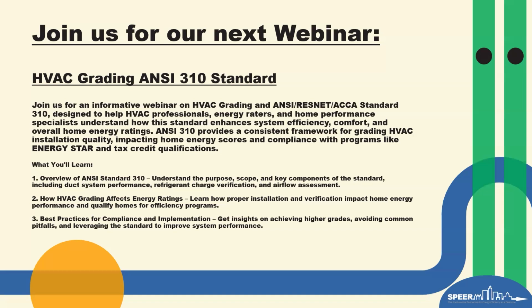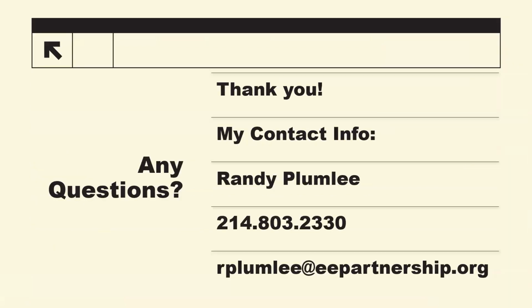If you're still doing the YD150s, if you're in an area that's on the 2018 or prior, 2015, 2012, 2009, and you have mechanical ventilation, then they're going to be doing open heart surgery if they need to test it for Energy Star. However, if you have 2021 and beyond, you really need to be having these inline fans that come with test ports so that you don't have to do that.